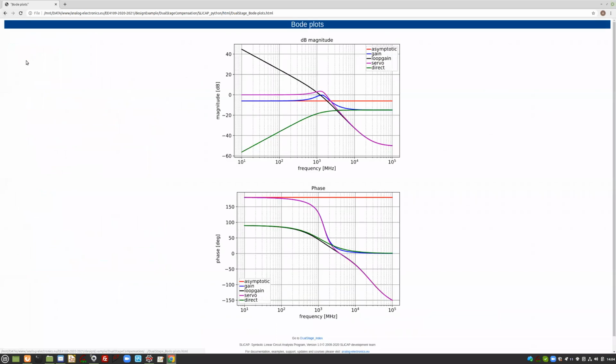Maybe again the Bode plots, but now a little bit larger. So here you see this 1.4 gigahertz is where about the peaking happens. The blue line is the gain. The black line is the loop gain. It crosses the 0 dB axis there where you have this peaking, where you have the bandwidth. The loop gain reference is correctly chosen because you see the asymptotic gain is frequency independent and minus 6 dB. That is exactly what we expect for the ideal gain. So that is basically, sorry, for this small signal behavior that we already did last time, but now we did it with some new values, and we showed how to do it with a simple hand calculation.